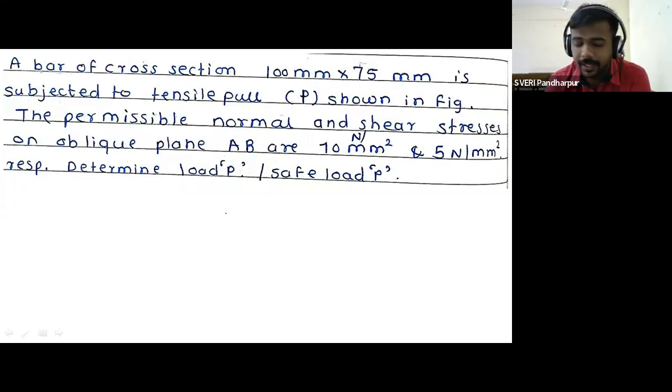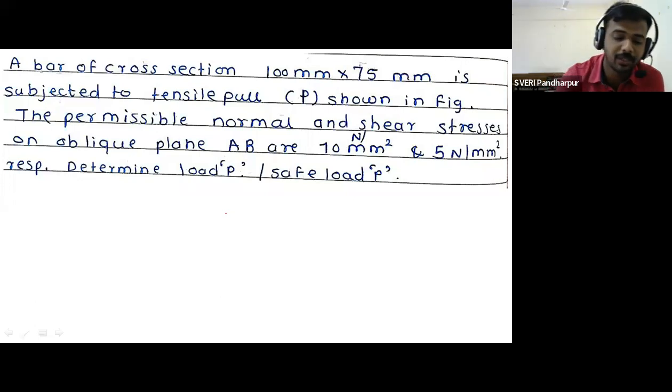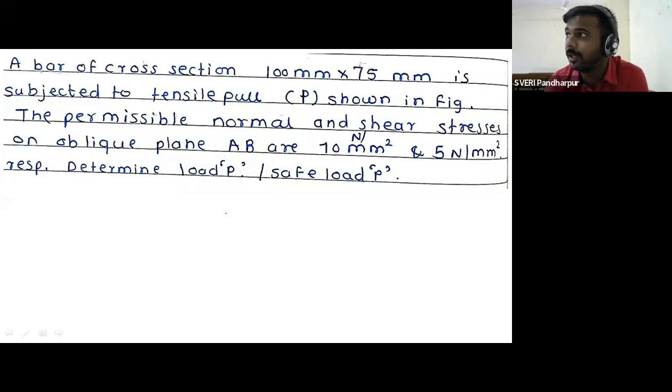and why this particular chapter is important as far as the calculation of the stresses on irregular shapes or the inclined surface, which is also called the oblique plane. In the previous lecture, by taking the reference of one rectangular body, we discussed all the important definitions. That is, why sigma x and sigma y are called the principal stresses, and if your member or body is subjected to the principal stresses, how to calculate the normal and the tangential stresses on the oblique plane and